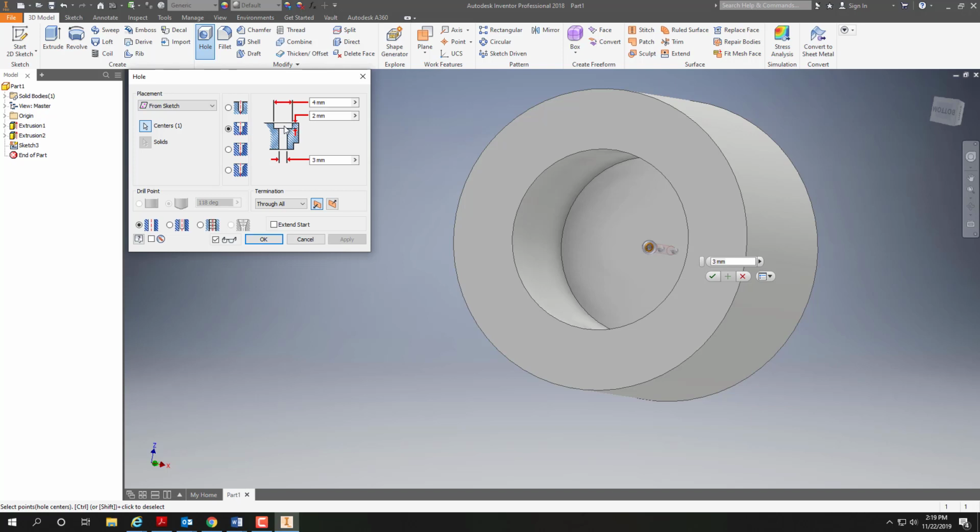But notice here, the counterbore itself is wide enough, the diameter is large enough, so that the head of the nut, a hex nut or whatever, will fit in there, and it's deep enough also so that if there's another part sliding over it, it will not hit that, okay?